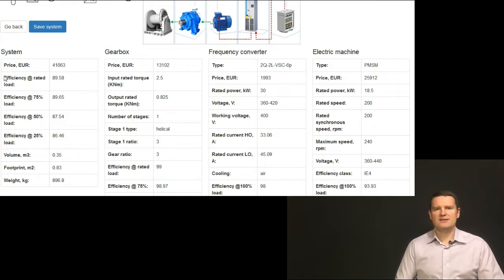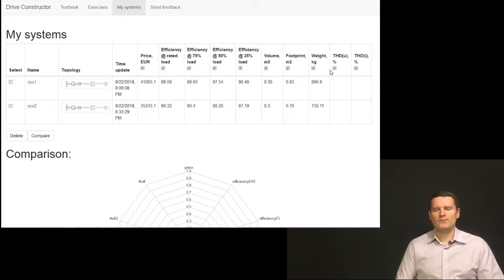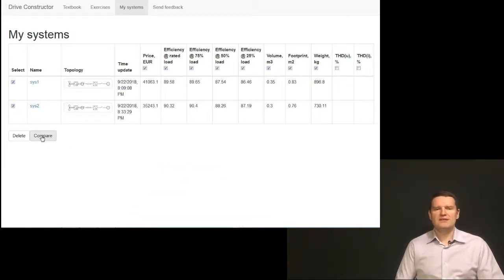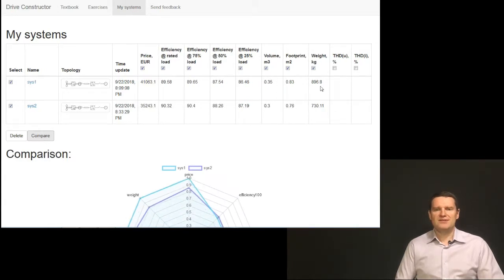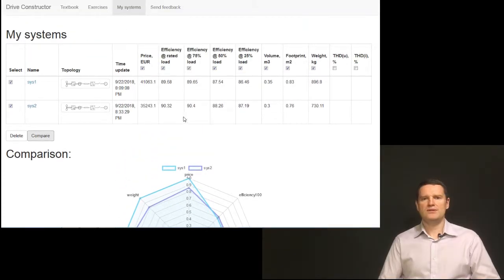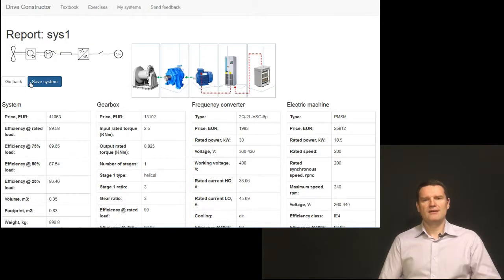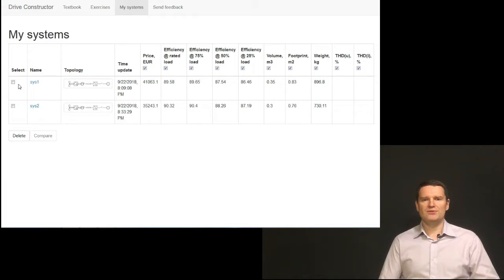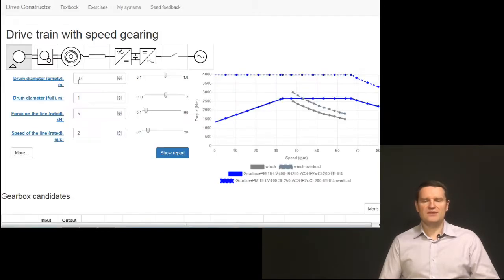In the sizing results, summarized in the report, one can, for example, find efficiency of the components, including the values at partial loads. This enables system efficiency analysis for different load profiles. The report can also tell what certain equipment is going to cost. Comparing variants, benchmarking, is an important element of decision-making on the way to the optimal system design. We can always go back and tune parameters again and again. This cut-and-try approach is the way to come up with your own design. This is very often the way systems are optimized in real life.